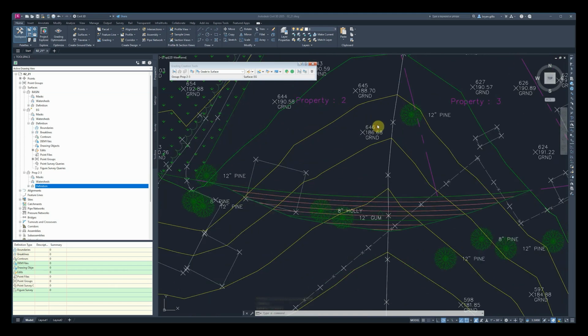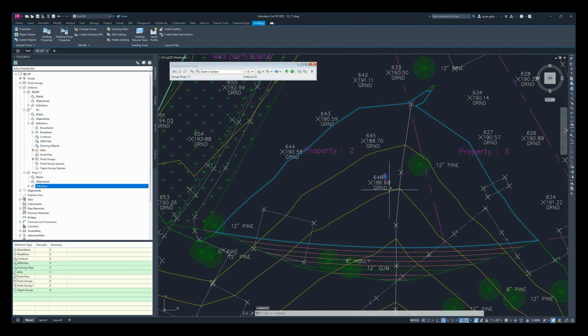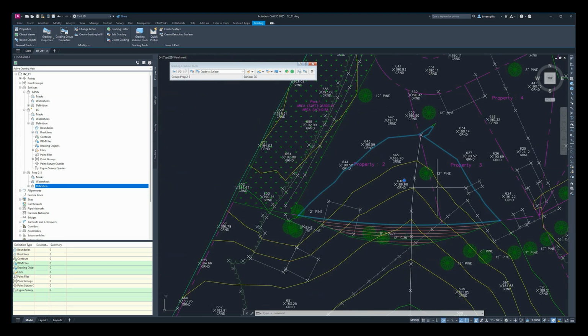You'll see this red diamond that showed up here. You can go ahead and select that red diamond next to 0.646. Zoom out if you need to. And you see this whole new surface, or this area that was just created, because we need all of this to be 0. So that's what we just created. You're not getting those lines because we're not actually doing any cutting here. What we need is all of this to be removed, because we see our elevation is trending higher and higher as we move further into these properties, and we want to make sure this is a nice, relatively flat home site.